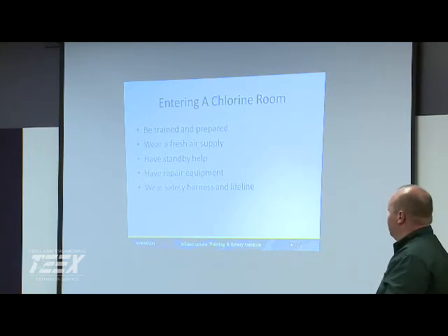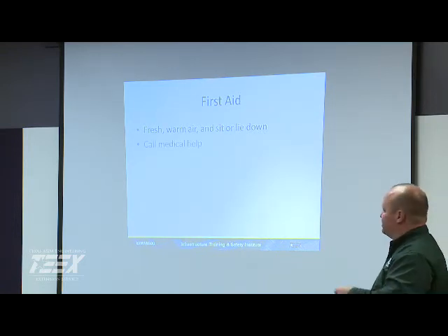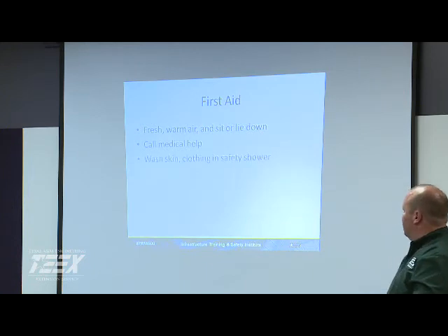Set up your perimeter. First aid, if you do get hit with gas, you want to get them out in the warm air. Obviously, the chlorine is cold, you want to get that temperature up. Try to have them sit up as best they can so they can off gas.